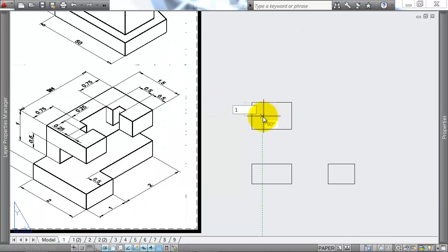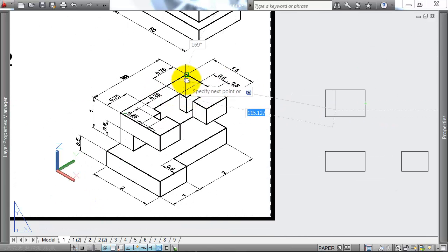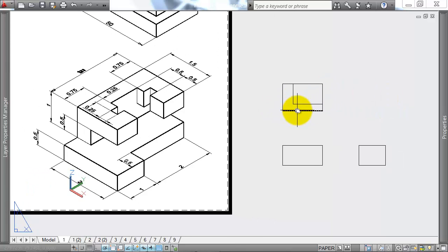You can see I'm not trying to visualize the whole shape at once. I'm just going one line at a time. I've got the box that everything goes in, and then I can measure across tau, and if I want to locate this line, I measure 1.5 units long, and for a construction line I'm just going to come the whole way back across the front there.